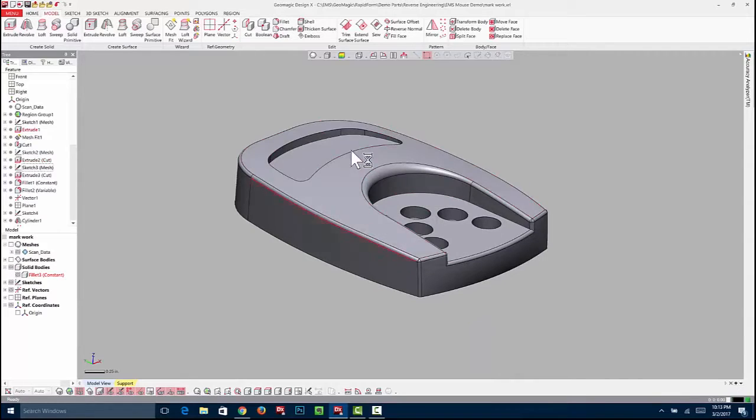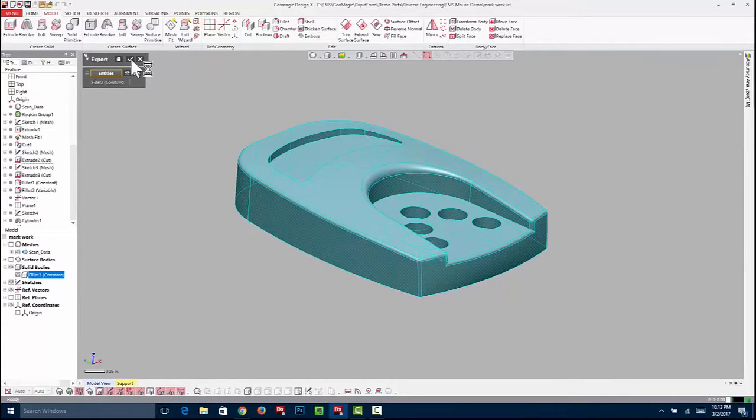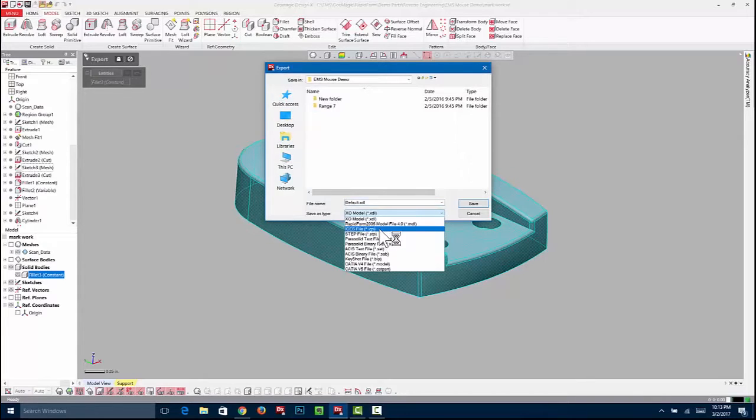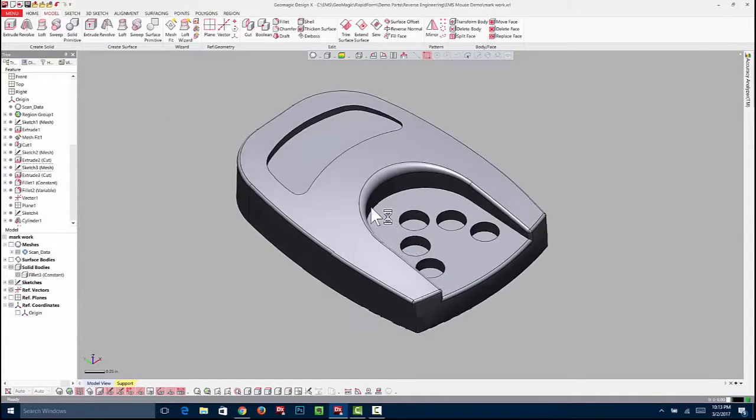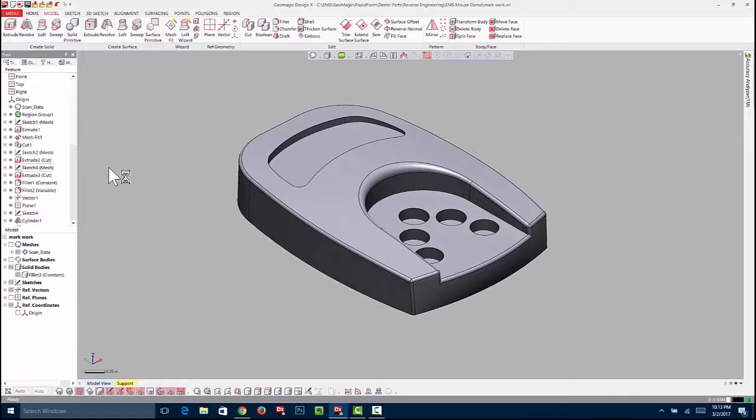Now I have a feature solid model, and if I hit extract and pick this, now I have formats like IGES, STEP, Parasolid, etc. Okay, so that's what we really want. Now, I have two options here for exporting this model. One is just to do what I showed, which was STEP, IGES, and others, Parasolid, and now I have planes and cylinders and surfaces, and that'll go out to any CAD system, any downstream application.